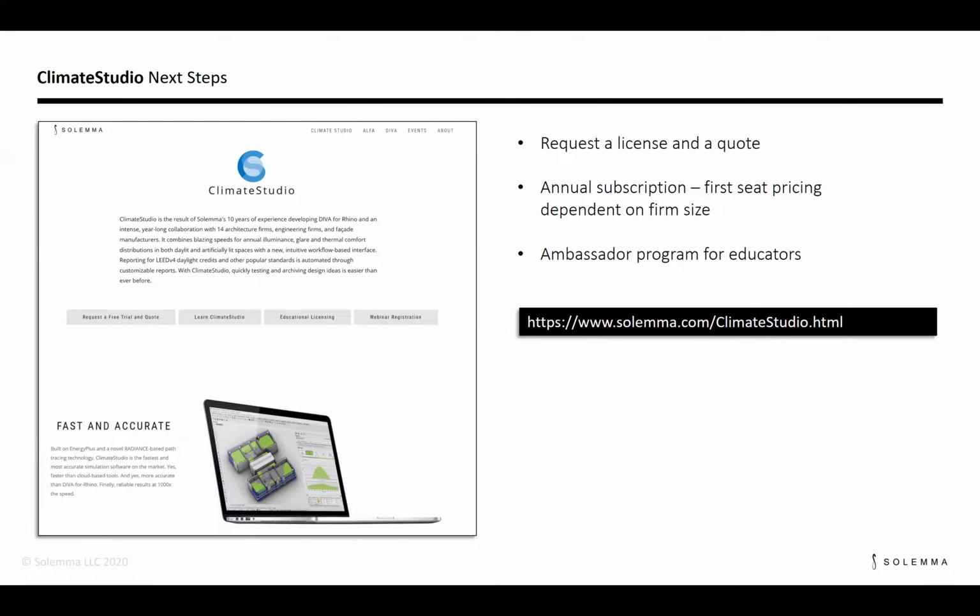Oh yeah, the question of what we are using. Are we using DAYSIM or different methods for annual calculations? We are actually using a version of the 5-phase method, so not DAYSIM per se anymore. For simple cases, DAYSIM and the 3 or 5-phase method should lead to identical results.